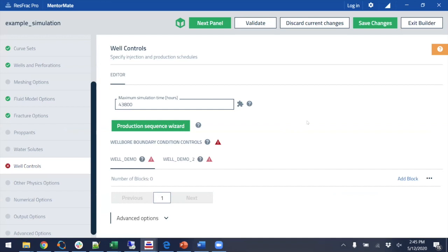I'll make another point, which is that if you have a lot of wells, you might want to synchronize when they change. This is something I just noticed, and I'm probably going to put in a warning or adjust the wizard to help people with this. Somebody sent me a simulation with 7 wells, and the wells were changing once a week, but they were all out of sync. So in practice, a boundary condition changed about every single day. And every time you change a boundary condition, it's going to slow down the simulator. It's going to take a bunch of time steps to capture that.